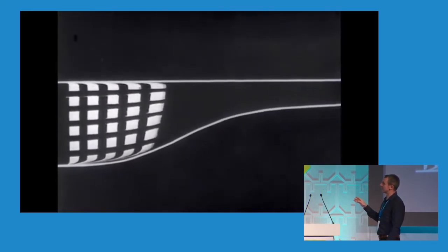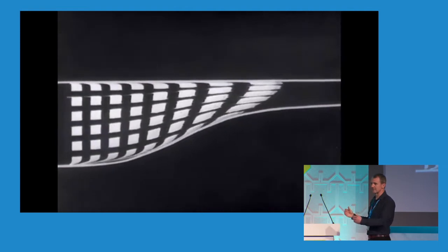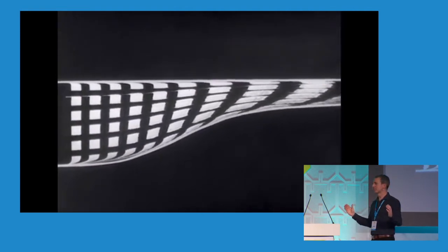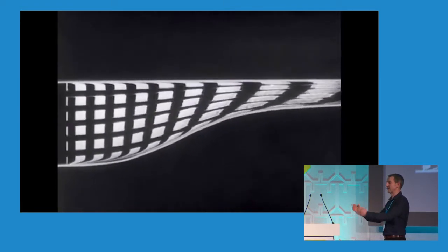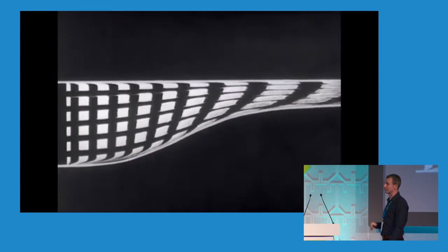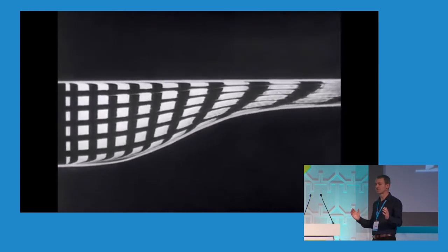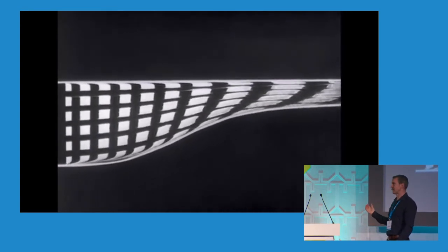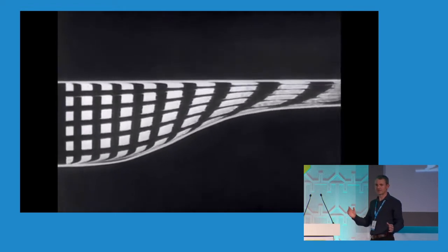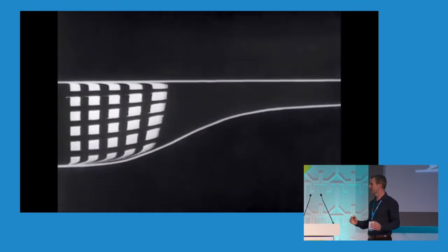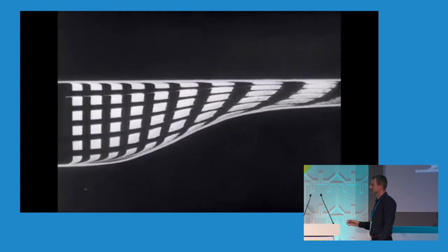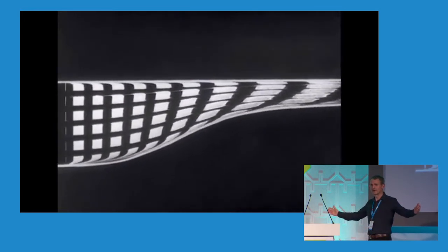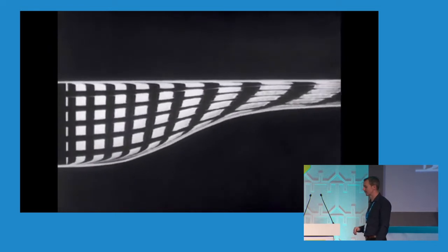And I think this also highlights the fact that that resistance is all down to the interaction with walls. So anything that's put in place on those walls that will reduce that flow and increase the friction is going to cause a big problem, and particularly when it's a small corridor. So things like bins and fire extinguishers, even signage and doorways, anything that's along those side walls is going to cause a big problem. Less so if you've got a really big corridor, but if it's really small, then that's obviously going to make a big difference.